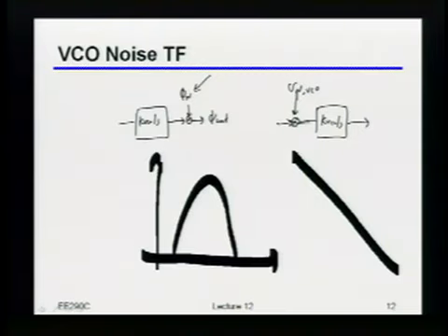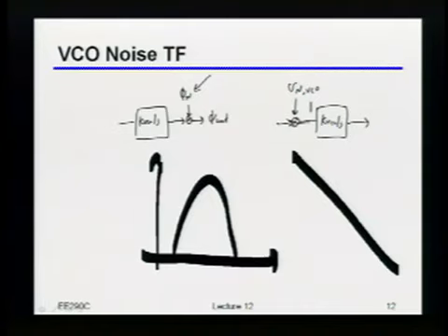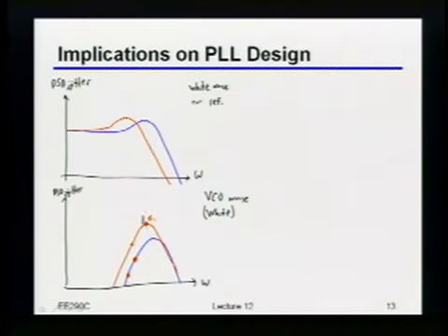Yeah. So what if the VCO has some 1 over F cubed noise or something? Then you can't. Well, okay, so that would say that, in this model that I'm drawing here, if it had 1 over F cubed noise, this wouldn't be white. It would have a 1 over F corner in it. Right now, that would say that basically this thing wouldn't just sort of go up like this, but at some point it would even have a higher slope on it.